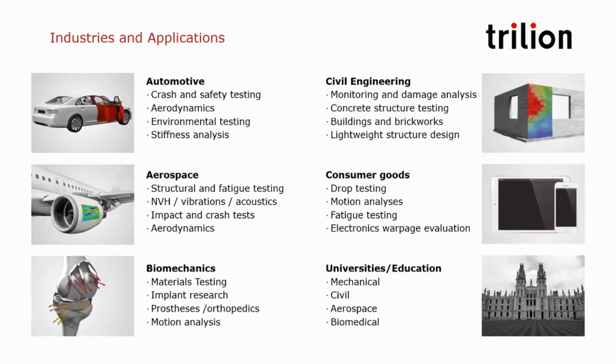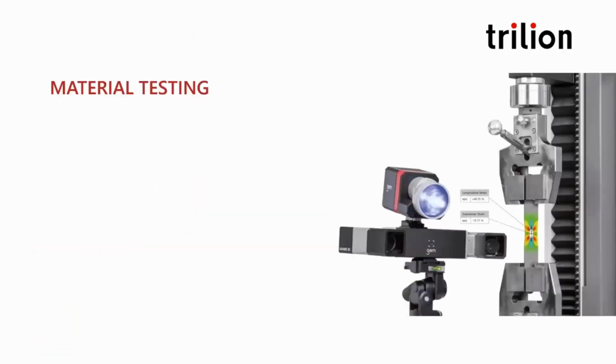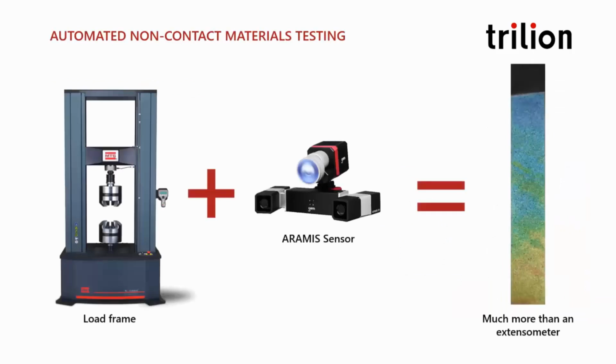And so today, I'd like to concentrate on a few case studies in the biomechanics realm and to more clearly understand the technology. So let's look at material testing first. We have 8 different input channels that allow you to bring in the load and synchronize your data. And so we can get some dimensional information and calculate stress strain curves, and we can follow ISO ASTM standards. And this type of setup is perfect for use with servo hydraulic machines or electric models, plenty of different load frames, or even in vivo applications, as we'll see.